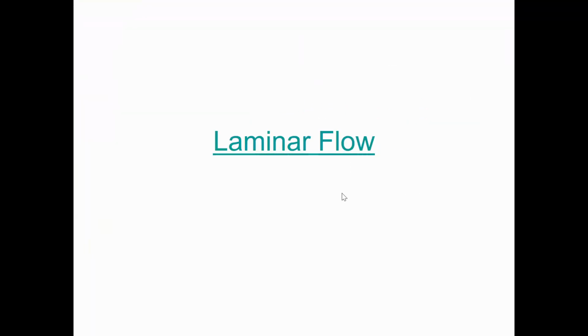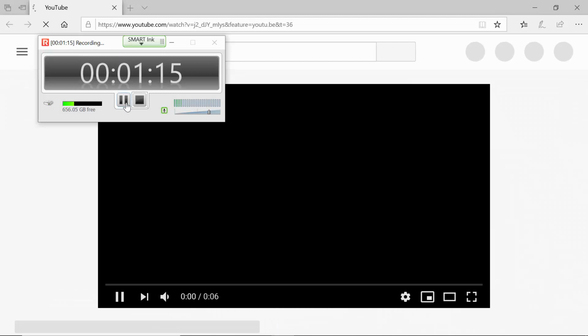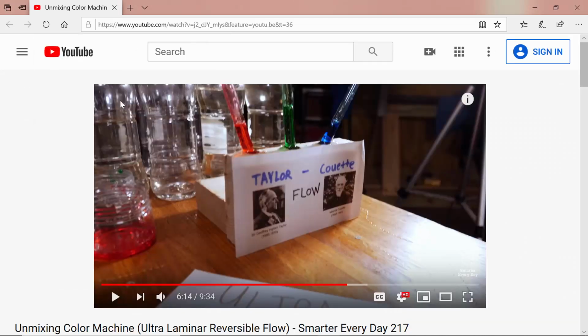Okay, so this is kind of an interesting video that I stumbled across recently having to do with laminar flow. Is when we have a non-Newtonian fluid, which means that the viscosity changes as a function of the shear stress that's applied. And so a shear thickening fluid would be one like the cornstarch mixture that we looked at, where when you applied a shear stress, the viscosity went up. What he's saying is that that fluid, the cornstarch, is shear thinning, and so the faster he was moving the dial, the viscosity decreased.